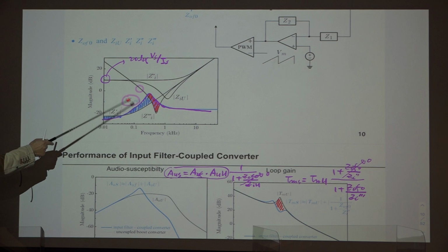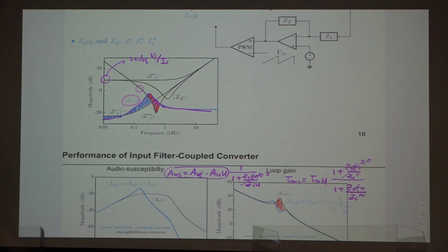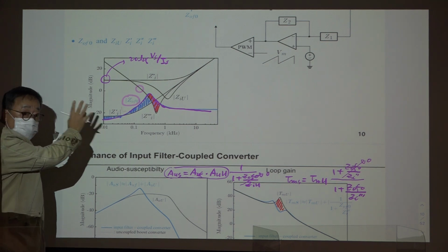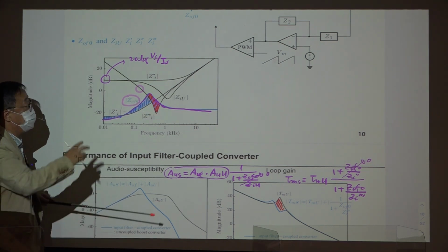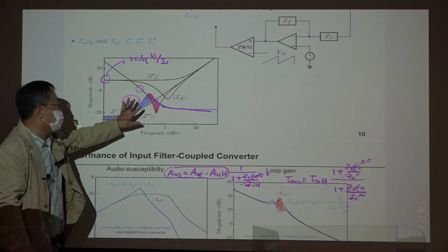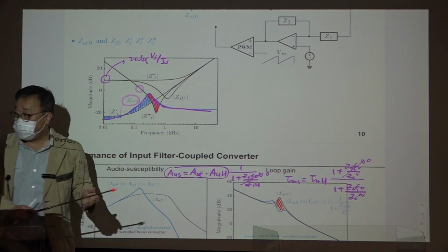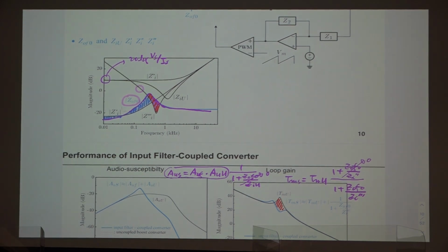Okay, so you are using boost converter with voltage mode control. That is very unusual. Okay, it is usually known that the voltage mode control is not adaptable to boost or buck converter. So voltage mode control is only good for the buck converter. But I'm using boost converter example to address the nature of these things. This is most pronounced for the boost converter case. But if you change the topology, you will have almost the same conclusion, same shape, all the impedances and the source impedance. Okay, so this can be considered general analysis.